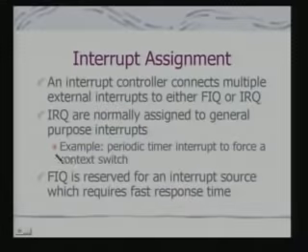In the case of this periodic timer, the latency is more of an OS consideration and not a property of the external signal. But when we have to handle a very fast external signal with low interrupt latency, that becomes a signal coming from some kind of dedicated peripheral or dedicated application. So, that interrupt is associated with FIQ.